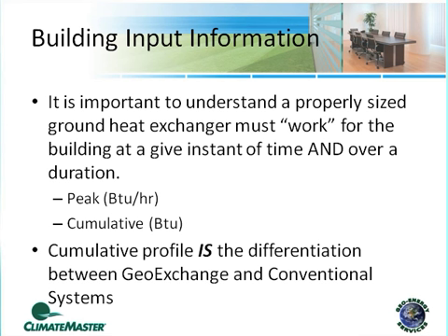But it's understanding that this accumulation, or this cumulative effect, carries through the ground heat exchanger design. I can't design a ground heat exchanger by just knowing the peak BTU per hour load only. I have to understand the cumulative. And here's how we understand the cumulative.